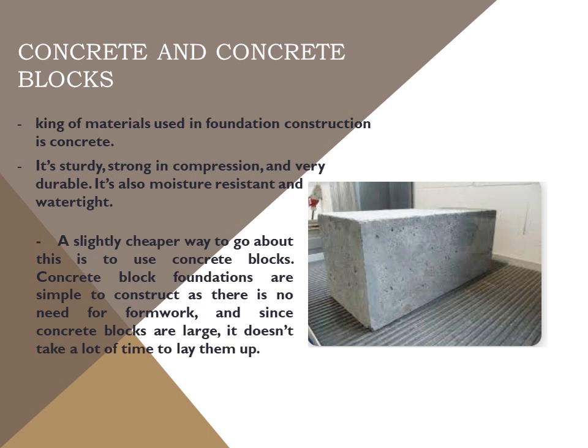Concrete and concrete blocks. The king of materials used in foundation construction is concrete. It's sturdy, strong in compression, and very durable. It's also moisture resistant and watertight. A slightly cheaper way to go about this is to use concrete blocks. Concrete block foundations are simple to construct as there is no need for formwork. And since concrete blocks are large, it doesn't take a lot of time to lay.